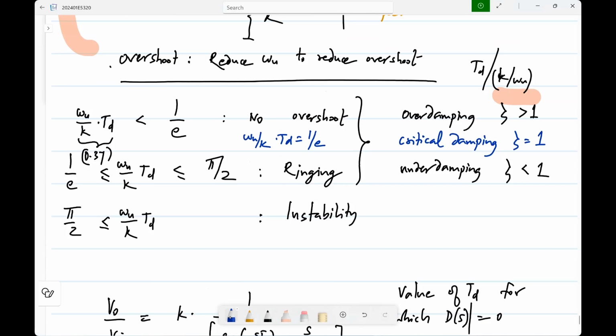So similarly here, some delay actually helps you in speeding up. But of course, if you have too much delay, you start overshooting. So this critical damping is when you have the fastest response without overshooting. So actually it is good to have some delay and you have this type of behavior. Is this fine?